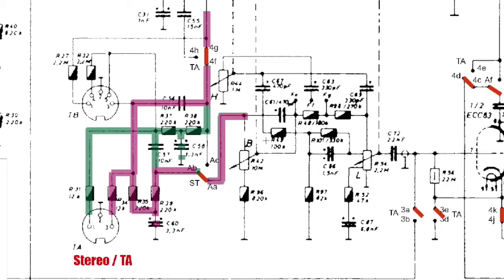So what we've actually done is we've kept the full range of the left and the right channel to the left and to the right, but we've also summed to each one of those the bass frequencies of the opposite channel. So what you have up here, for example, is the full right channel plus the bass frequencies of the left channel. What you have down here is the full left channel plus the bass frequencies of the right channel.